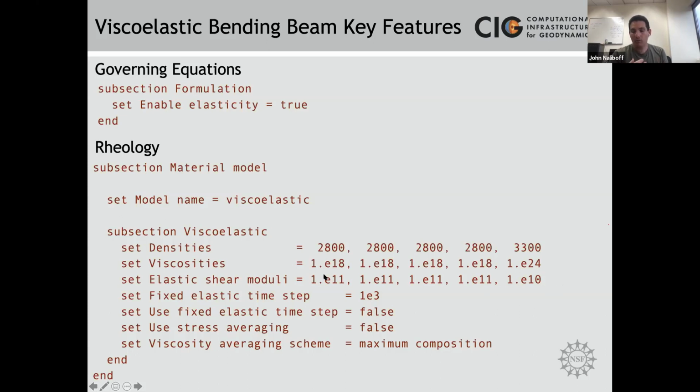And of course, if you have multiple lithologies, so let's say I had 2 different beams with 2 different properties, that volume fraction computation, or looking at what materials are present, would involve the background and 2 different beams. So it gets a little bit more complicated. But this is done automatically inside the material model. In this case, this would be a function the material model calls. And so in the viscoelastic material model, we set it up so that depending on if you're using 2D or 3D, in 2D you have 3 components of the stress tensor, in 3D you would have 6 components. The ordering and the naming scheme we use automatically removes these from the volume fraction computation. And so you don't have to worry about that. That's automatically taken care of.